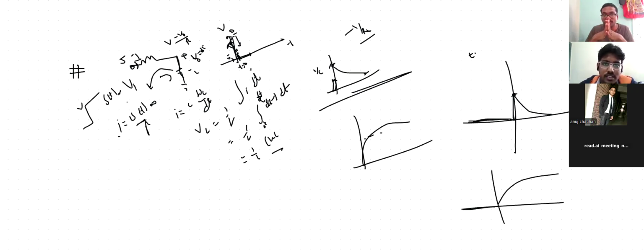If we do the impulse response and get the output, there won't be any extra pole in the circuit. Whereas if you do the unit step and ramp, it will introduce poles in the circuit. So sometimes some instabilities may come somewhere in the circuits. Also the impulse response is used with Fourier transforms. See, if you see this graph, this is the pure system response.